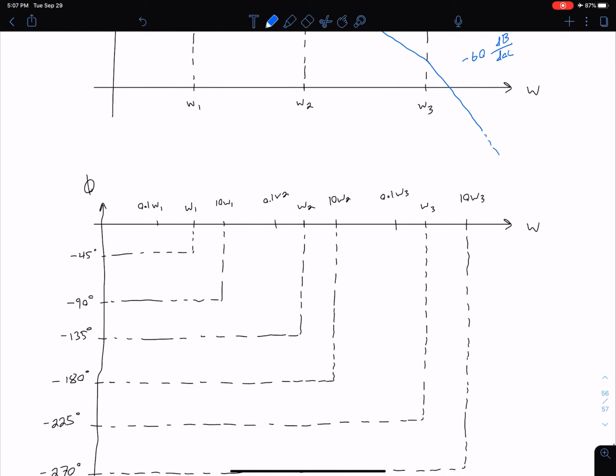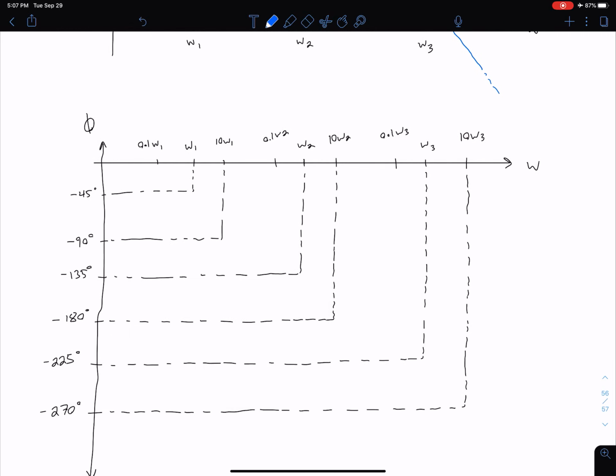So moving on to our phase then, we're going to use that information. We know that for one pole at omega 1, our first corner frequency, we're going to have negative 45 degrees. For our linear approximation, let's say once it gets about 10 times greater than that omega 1, we're at negative 90 degrees, and 10 times less, we're just at 0. So we have something that looks like this, and we just connect that with a linear line. I've drawn that sort of poorly, but that should be a linear line connecting those. And so of course the slope is negative 45 degrees per decade.